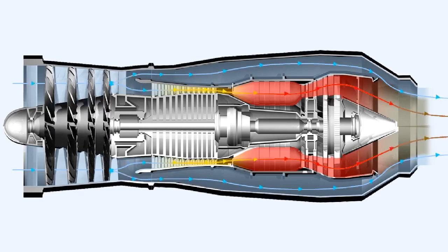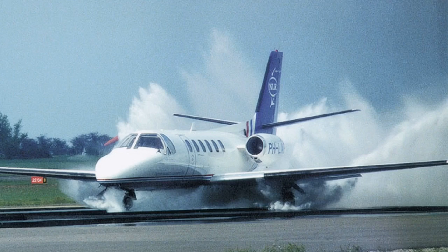During normal engine running conditions, combustion is self-supporting. The ignition system is actually switched off as soon as the engine has attained self-sustaining speed. Self-sustaining speed is the speed at which, after start, the engine can accelerate without the assistance of the starter motor. There may, however, be certain engine operating conditions which do require the use of the ignition system. For instance, just such a condition would occur following a flame-out, which is extinction of the flame due to various unusual occurrences, such as the ingestion of large quantities of water thrown up from the nose wheels into the engine intakes during takeoff from a heavily contaminated runway.